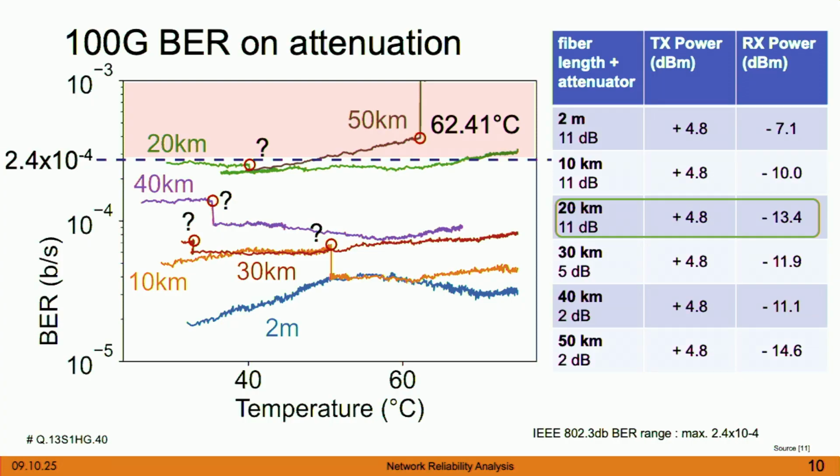But what is more interesting about this diagram, there isn't so much correlation to the temperature. With some exceptions, like you have some jumps. If the temperature goes up, all of a sudden it jumps down, and the bit error rate is better, which could be the conclusion that, well, if you heat up your transceiver, the bit error rate is better. Nah, it doesn't make sense, right? Well, it turns out that what we do in the manufacturing is checking the eye diagram.